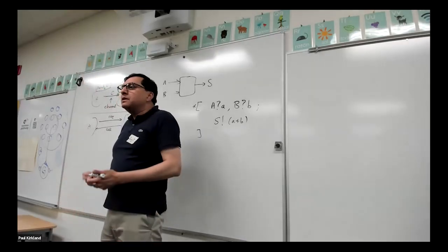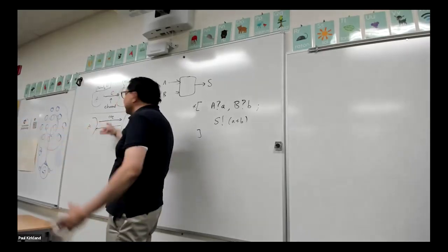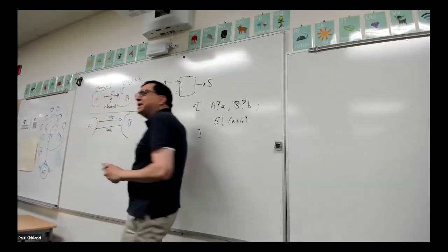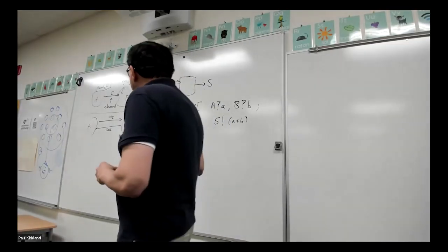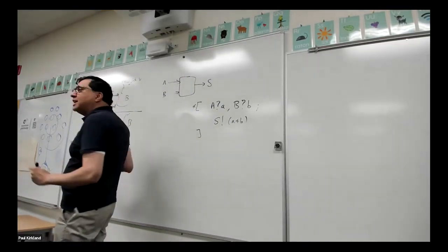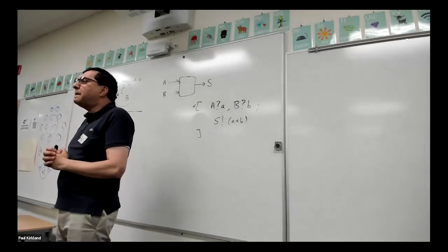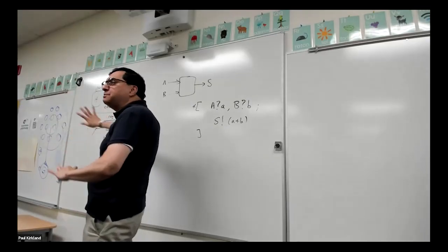So it's always a 4-phase handshake? No, these are all options. That's a 4-phase handshake. There's a 2-phase handshake, and there's even a 1-phase handshake. I'm not going to explain how it works. That means you still have a clock somewhere, no? No. All you need is some set of gates that can generate the signal correctly. You don't need a clock. If you have multiple bits, let's see how you have data. Here there's no data. This is pure synchronization.